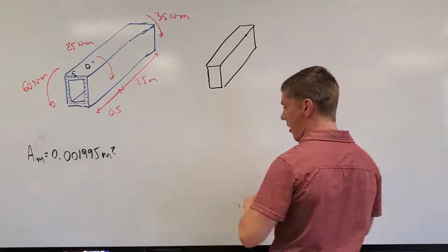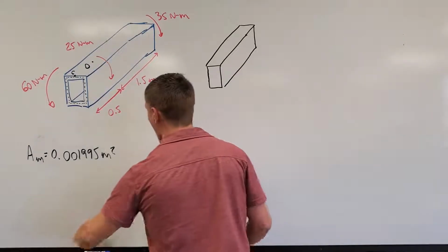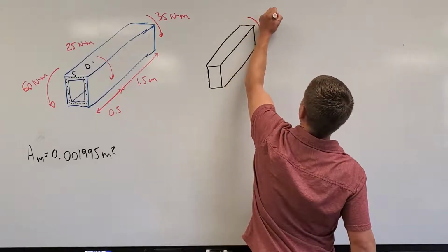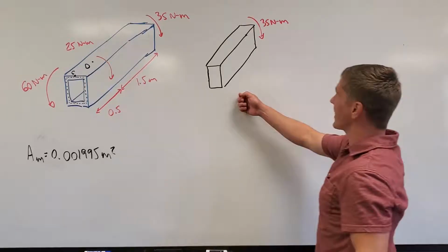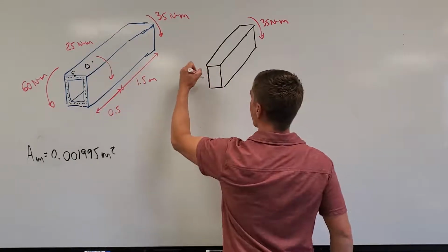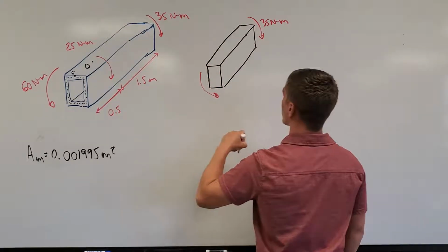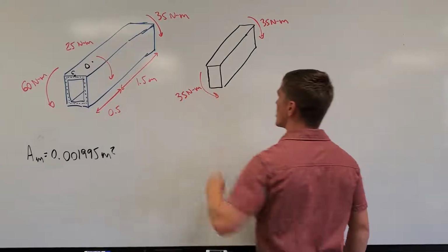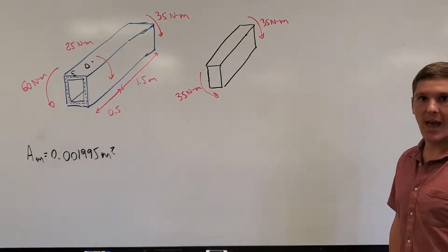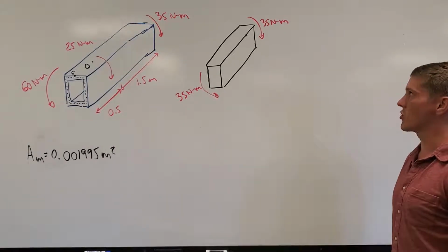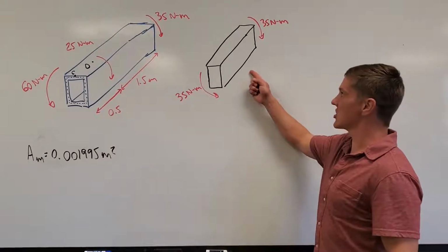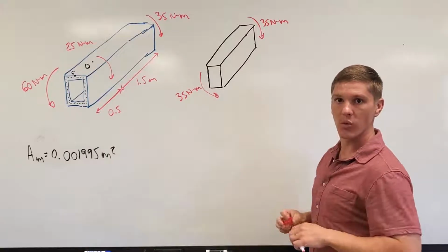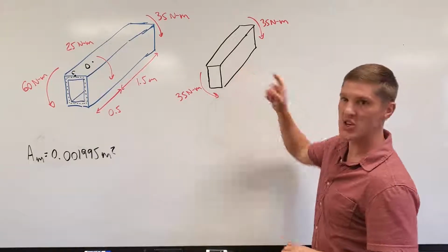Okay, at the wall, we said our reaction torque was 35 Newton meters. And if I made my cut at point D for equilibrium, the internal torque applied to this free end is going to also be 35 Newton meters, just in the opposite direction. It's going to be a counterclockwise 35 Newton meters. Well, this just becomes one shaft with just a torque applied to the end, and this is what we derived our equation for rotation at point D.